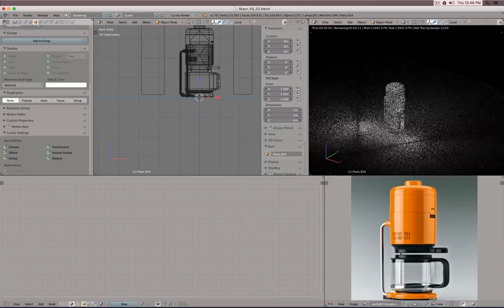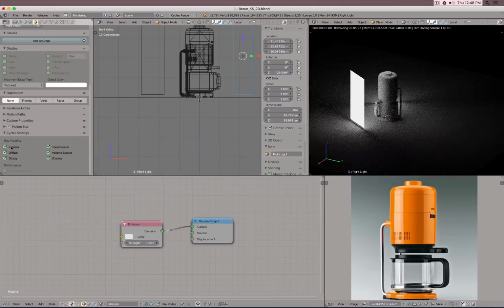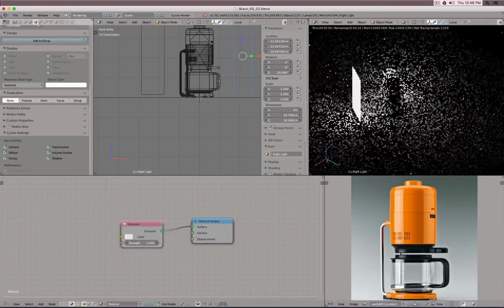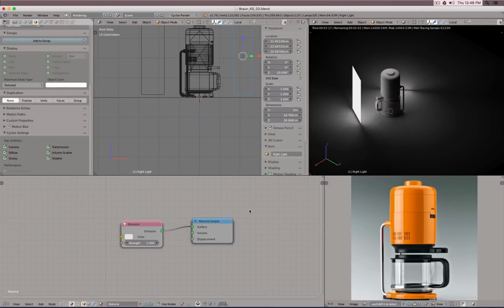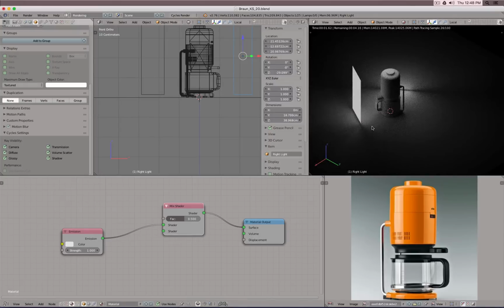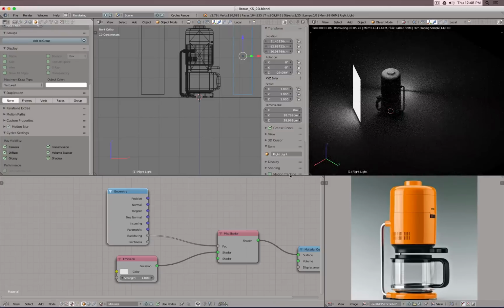There's one thing left we should do to our light sources. You see actually that each light source emits light to each direction, because it's a flat surface, and we only wanted to emit light into one direction. So what we will do simply is add a mixer there. And then we would like to tell the software, well, pick one surface of my object. Let's say here the back facing.